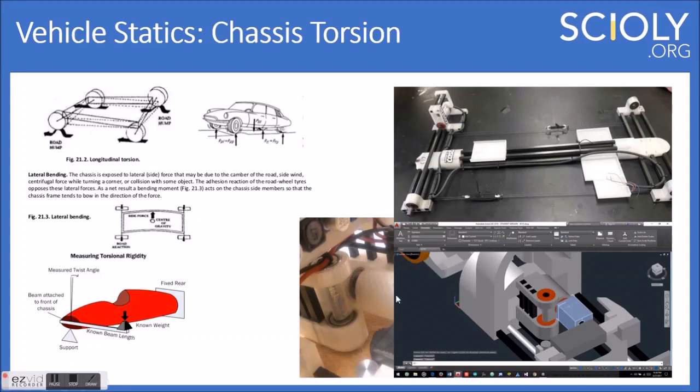I think over here, you can see this free rotation. This was where the caliper was getting attached. You can see in this CAD model, and it was free to rotate inside of this part, so that helped with the torsion as well, in that the front could actually slightly rotate, not just turning the axle angle, but also rotating so that the wheels can maintain different contacts depending on if the angle increased or decreased. It's kind of difficult to explain, to be honest. I don't really know exactly how important that was, but it seemed like it was helping the device, so I just thought I would mention that.